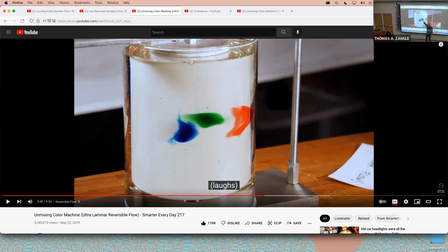This thing started out as a nice little uniform blob, but it's spread out a little bit, not because of fluid mixing, but because of molecular diffusion. That effect would be much larger in water, because molecular diffusivity is higher in water. But in theory, if you go incredibly slowly and nothing else is causing the fluid to move, it should work with water.